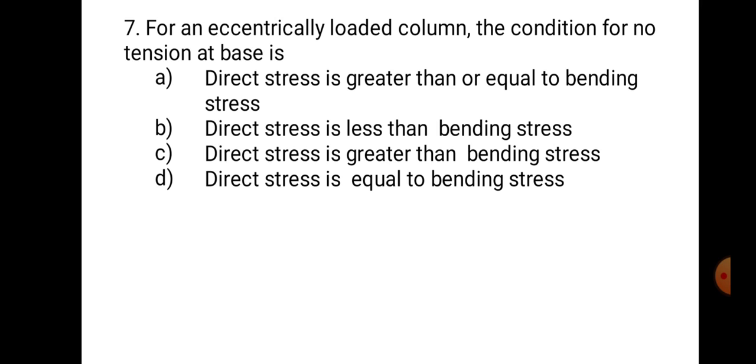Now, for the condition of no tension at base, the resultant stress should be of the same nature throughout. Now here you have to think that option A and option D are very near to the answer, but which is the correct option? Because in A, direct stress is greater than or equal to bending stress, and in D, direct stress is equal to bending stress. Now the condition asked should be applicable for all the circumstances.